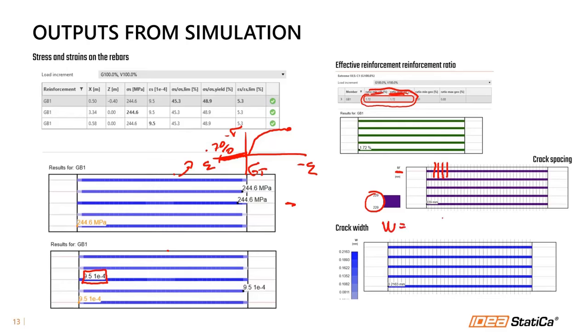If you would like to calculate the crack width, you've seen that on the first page there is an integral of epsilon m minus epsilon cm, which is the averaged contribution of the tensile strength in the concrete along a very small distance dx. So it's just the integral in between the cracks, or in between the crack spacing, that gives you the crack width.